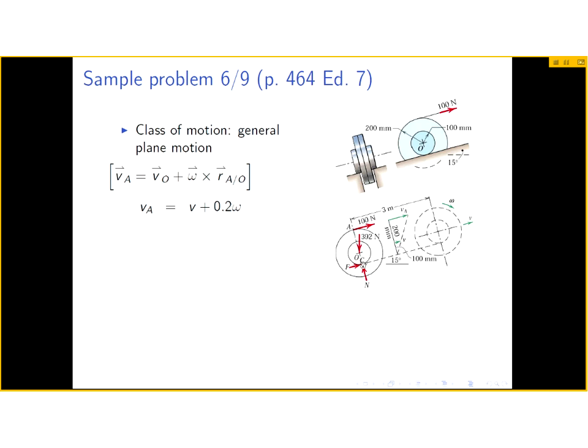Now you shouldn't think of the fact that the contact point actually moves up the incline as an indication that the friction force moves. It is as if it's a new friction force for every new contact point. The friction force would move if the two surfaces move relative to one another. That motion would be associated with work being done by the friction force.